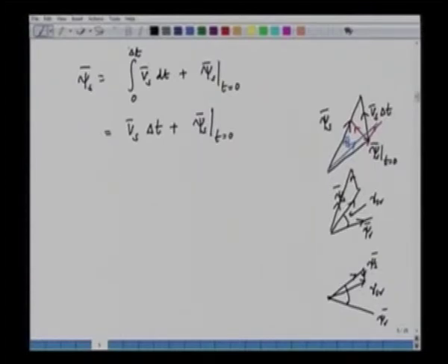So, we have the freedom to choose any one of the 8 voltage vectors, and thus we can control the stator flux accordingly. If we can control the stator flux, we can control gamma SR, we can increase or decrease gamma SR, and if we increase or decrease gamma SR, we basically increase or decrease the torque, and hence the torque of the machine is controlled directly, hence the name direct torque control.